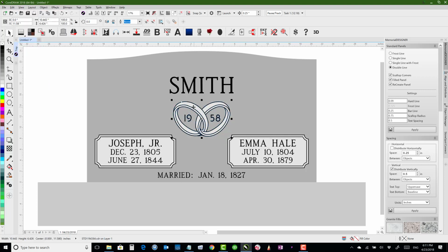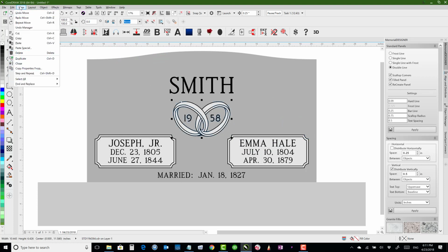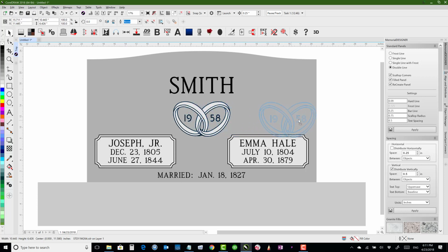Dynamic guides are more like the guidelines, I think. And so you can see as I bring this up, it's created a guide, like a 45-degree angle guide, so that I can drag it across that guide. Maybe I'll turn off alignment guides so you can see the difference.